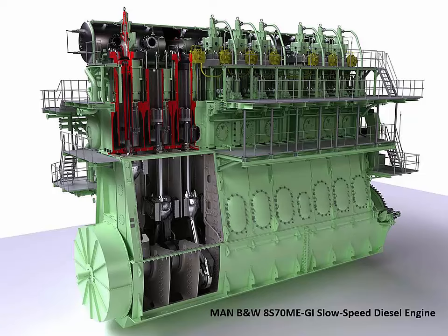There is enough force on that propeller that you can easily expend all your start air bottles and not be able to start the engine. So another limitation is that above typically around 8 knots, you cannot reverse. So what the mates will do typically is to try to reduce the speed of the vessel. You'll go hard to port, hard to starboard, and that corkscrewing movement through the water will reduce the speed of the vessel, and then once you're down below the 8 knot level, you can go ahead and start the engine.